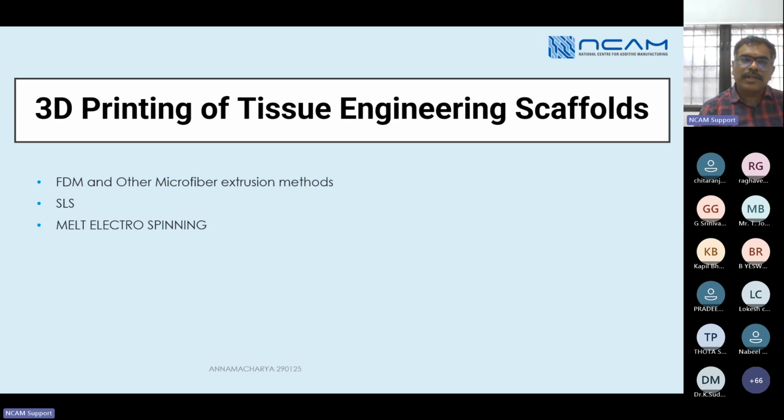And if you go to SLS technology, SLS is also used for development of scaffolds, especially for prosthetics or any other thing where you need scaffolds for prosthetics. Scaffolding designs and everything are being designed, and then you get the object 3D printed in SLS technology. And melt electrospinning is one popular technique being adopted with 3D printing, and they are right now taking advantage of it because what we were previously doing in the electrospinning technique is now popularly called a 3D tissue engineering scaffold fabrication technique, an alternative to the previous solution electrospinning technique, which is called SES.